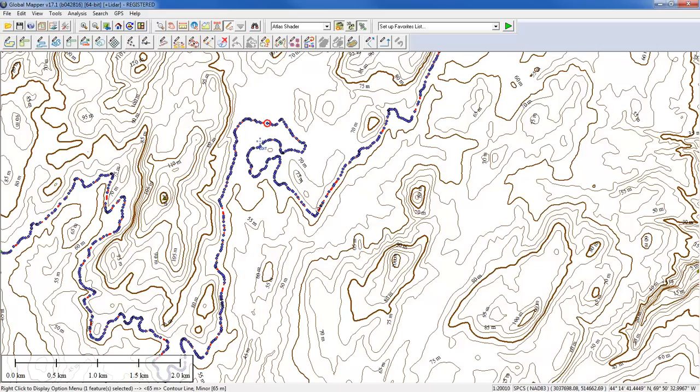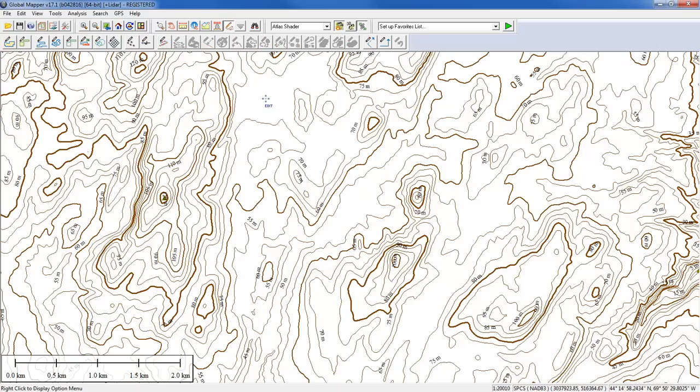Remove some vertices manually if that's applicable. You can redefine the visual appearance. They are obviously inheriting a default appearance. These brown shades are defaulted within Global Mapper. So there are multiple options as far as editing those vectors are concerned. And ultimately, for many users, exporting these is the next step.